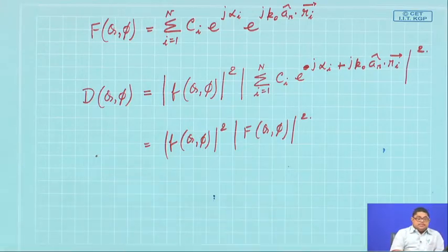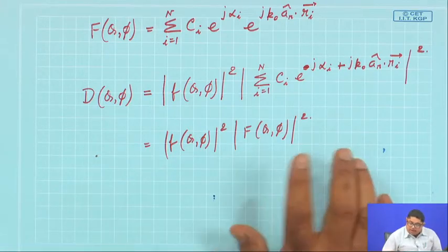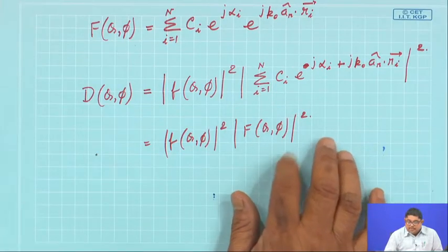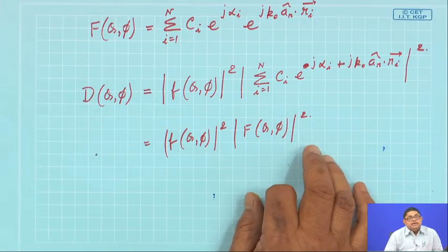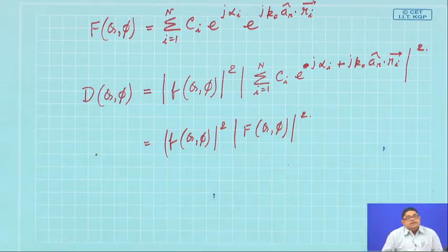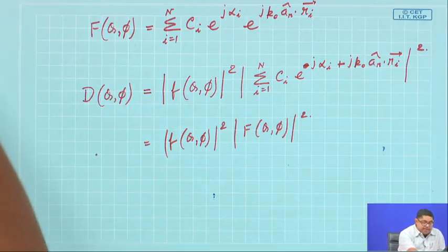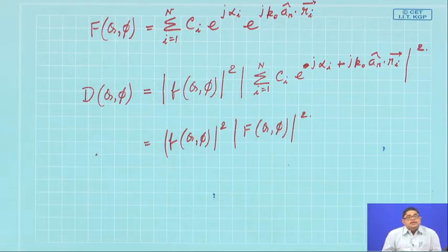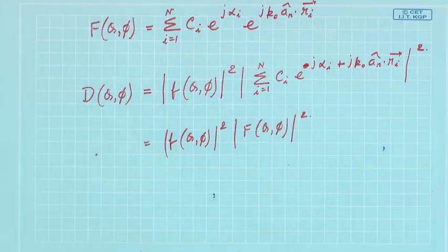So the total directivity will be this thing, but finding the directivity from the array factor is not so easy. We will see some simple cases where we can approximate it, but the end result is that directivity increases much because of the array. That is why arrays are used to give directivity in particular directions, and typically a 10-15 dB increase in directivity can be achieved with very simple practical arrays.